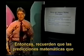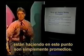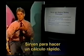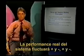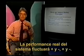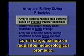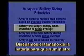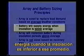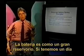So keep in mind the fact that the mathematical predictions that you're making at this point are simply averages. They're conveniences for you to use to make a quick calculation. Actual system performance is going to fluctuate plus and minus. So we size the array to meet the load based on average weather requirements. We size the battery to supply energy when the insolation is below that average. The battery is like a big buffer, a big reservoir.